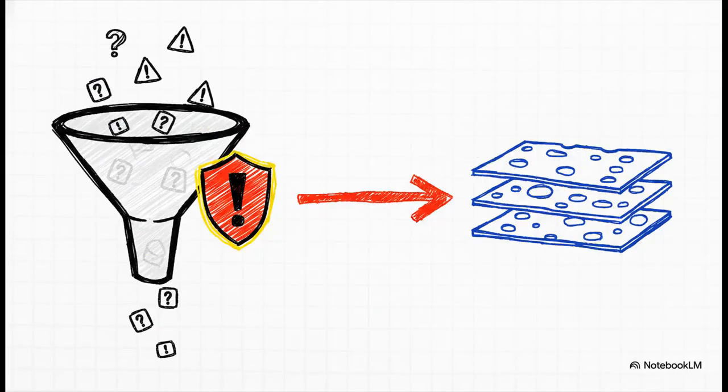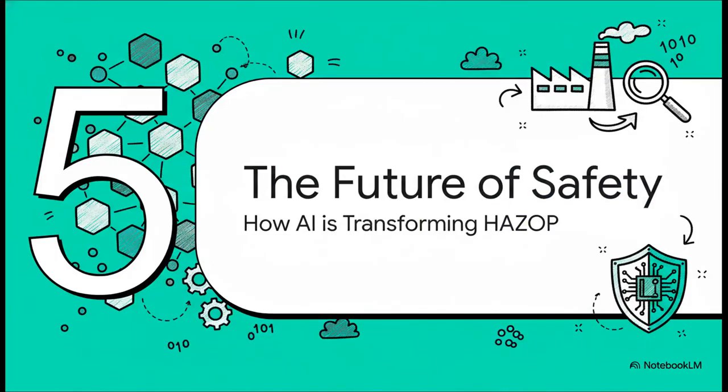And this is really important. A HAZOP is often just the beginning of the journey. Think of it like a big funnel that identifies all the things that could go wrong. And when it flags a really high-risk scenario, that usually triggers a more detailed quantitative study like a LOPA, or layer of protection analysis, to really dig in and make sure all your safety layers are strong enough to do their job.